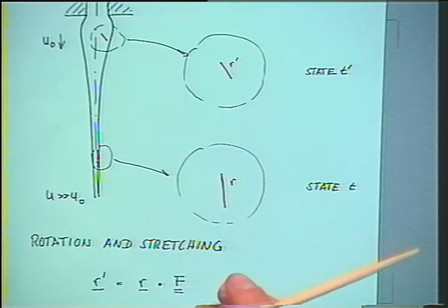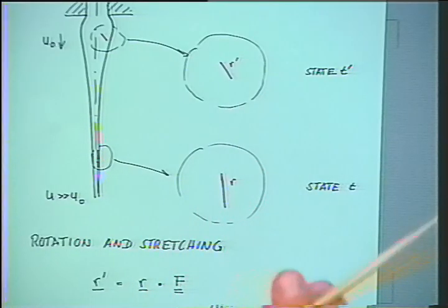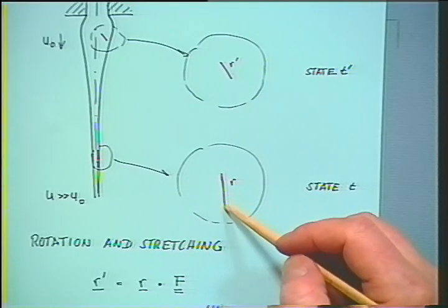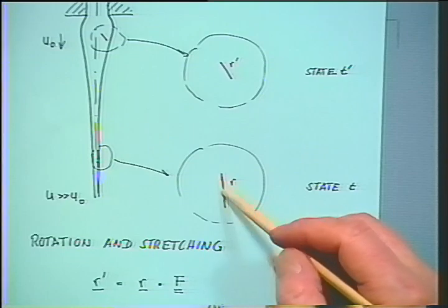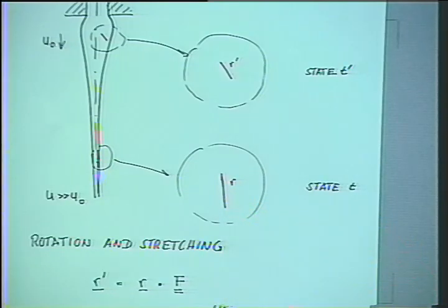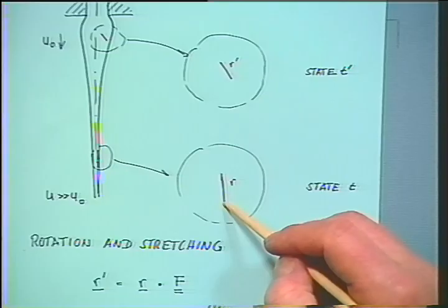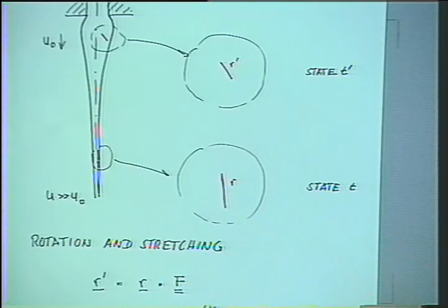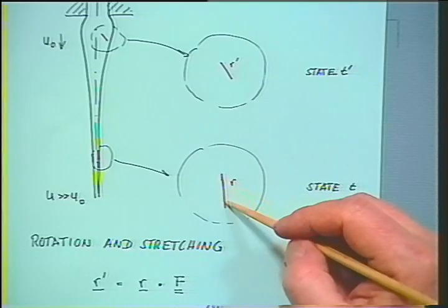The flow is called irrotational flow, but still material elements in that flow, when they elongate and when they change their dimension, require angle changes for those little material lines. And that's really the reason why the molecules in fibers are highly oriented, because the segments of the molecular chain are also oriented during that fiber spinning process.